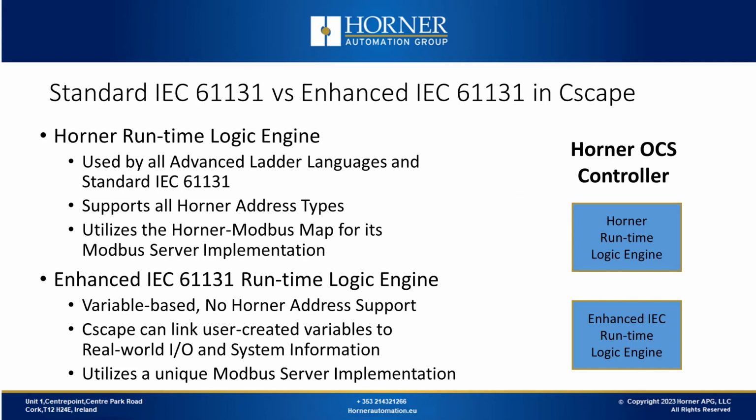Now we'll look at the difference between standard IEC and enhanced IEC in the Horner controllers. The standard runtime engine, present in almost all OCS controllers, supports variable-based advanced ladder, register-based advanced ladder, and standard IEC languages.